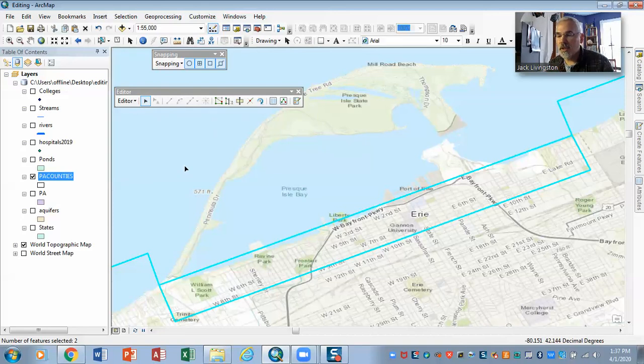In other words, splitting a polygon requires that you first go to the edge of the polygon, move interior to it, and then move to another edge. That way we're essentially splitting it. We could split a polygon a number of different ways. You'll notice, for example, I could simply click here and here, and double click, and I've split it again. However you want to do that.